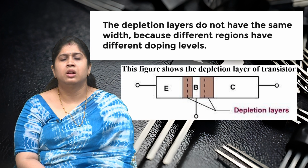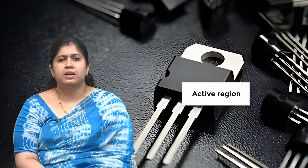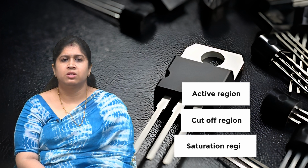In this figure, the depletion layers do not have the same width because different regions have different doping levels. This figure shows the depletion layers of the transistor. Depletion layers are between E and B as well as between B and C. And there are three regions: the first is the active region, the second is the cutoff region, and the third is the saturation region.